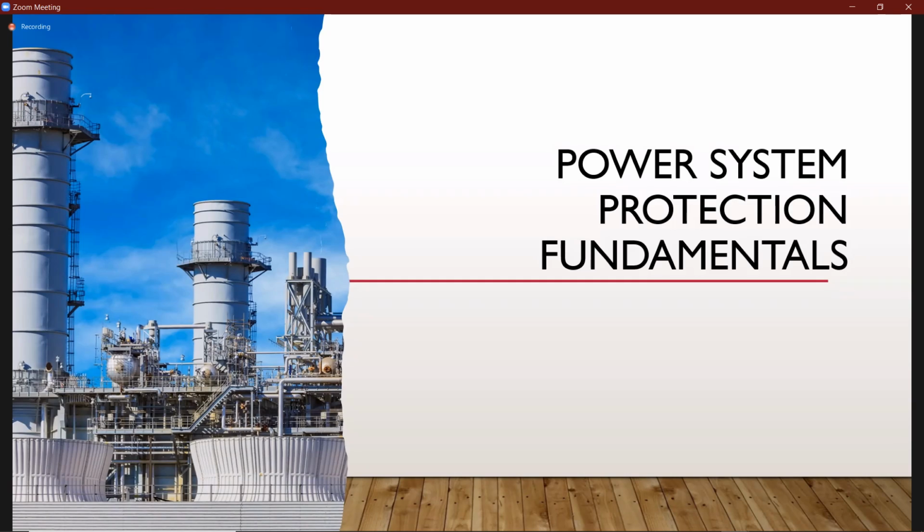And so point 5 then went on to speak about doing the tests on the bus bars to determine which one of them had the highest fault currents. This was a follow-up from what you would have done up to point 4, because by the time you completed part 4, you would have recognized that the highest fault currents would occur at the bus bars. So it is really in the substations or at the bus bars that we would do our analysis.